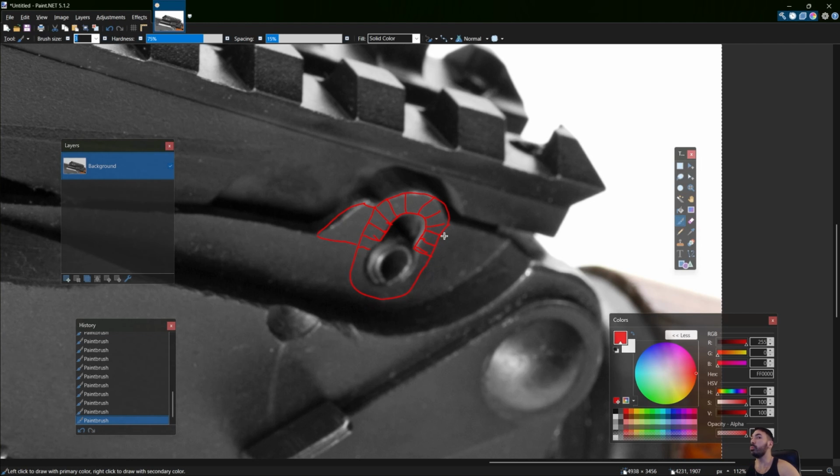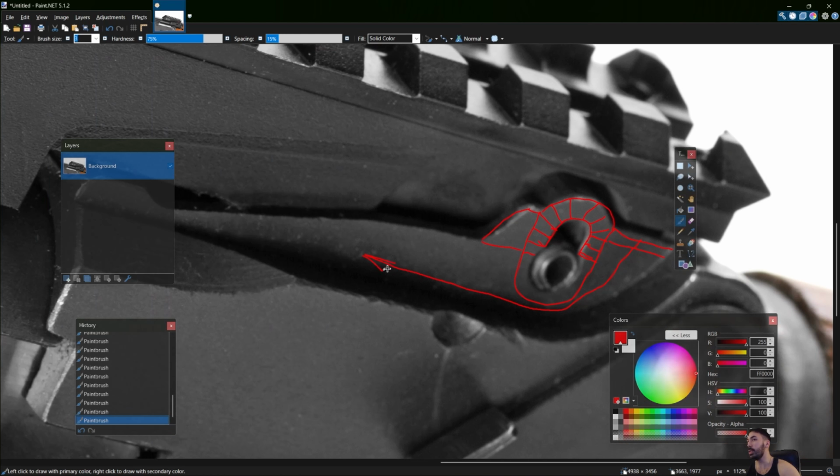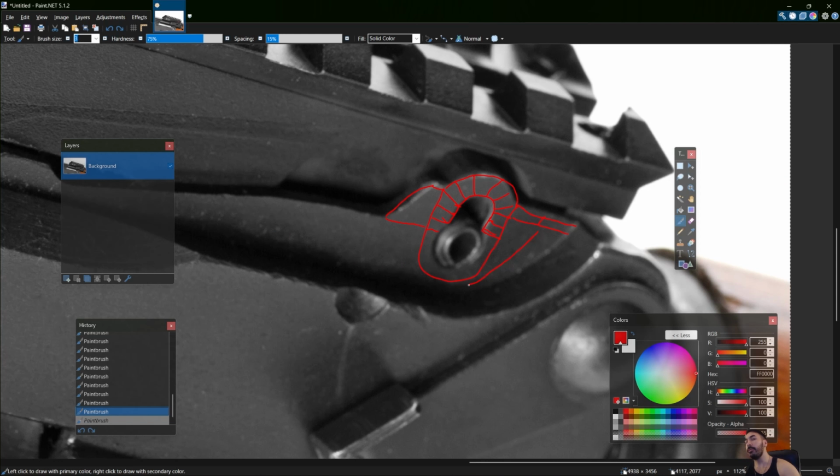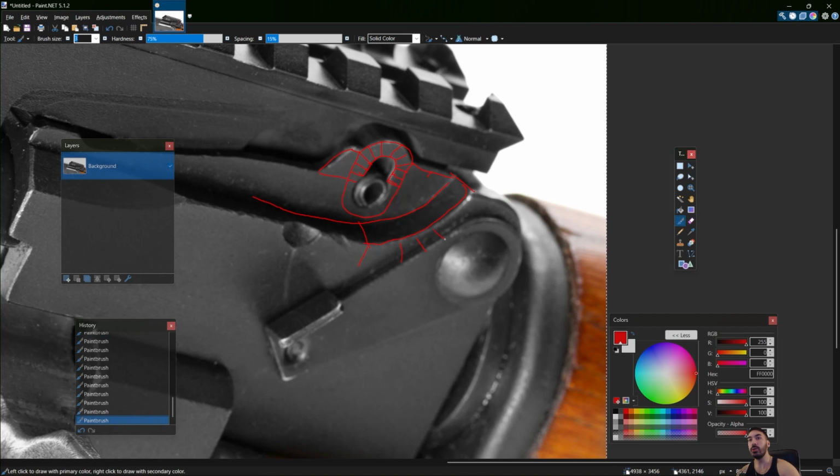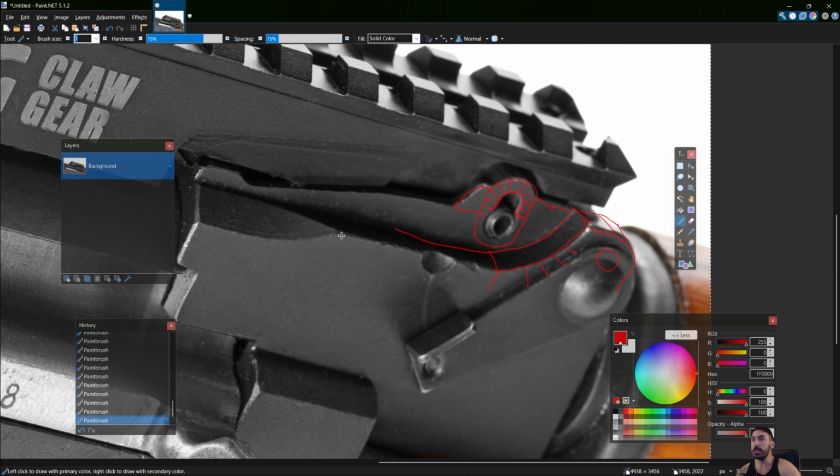And then the other thing we have to point out before we continue is that I want to have at least 2 segments over here on this side, because one face would be very long and thin, and those faces are going to flow in this direction and hopefully continue all the way to the end of this surface right here. I might be able to make that flow back here and then up like this, but I'm not sure if we're going to be able to do that. But the main thing here is we need to have very consistent geometry on this edge to allow for the creation of this little quarter of a circle, or a quarter pipe if you will. And then that geometry has to allow us to create a little circle which is going to be over here. And of course there is another quarter pipe over here on the front, so that's just something we have to keep in mind. Now these parts might look complicated to you, but believe me, these parts are probably the easiest.